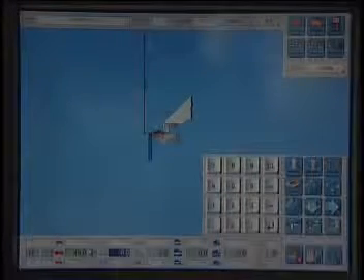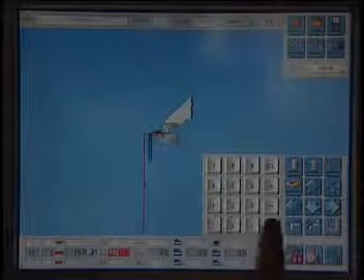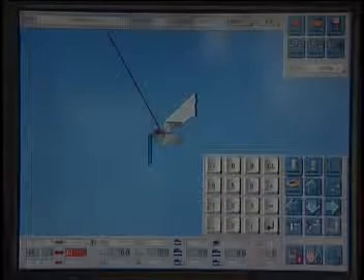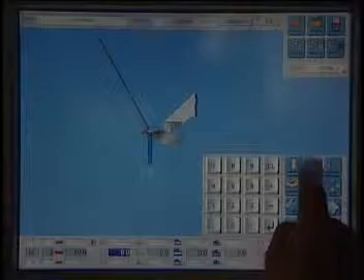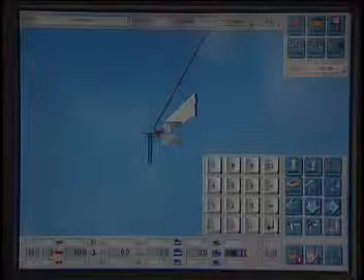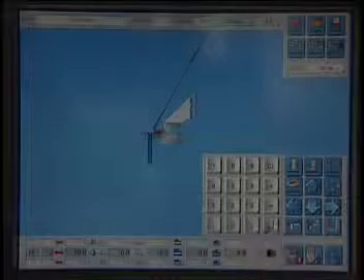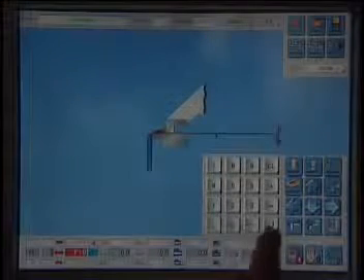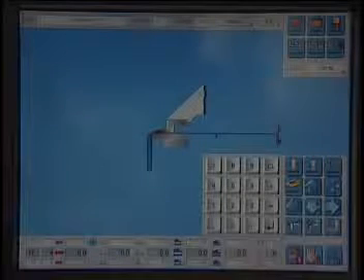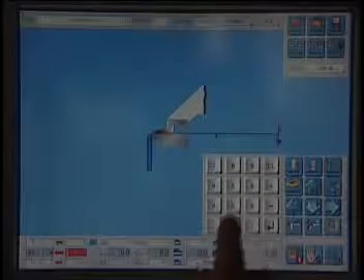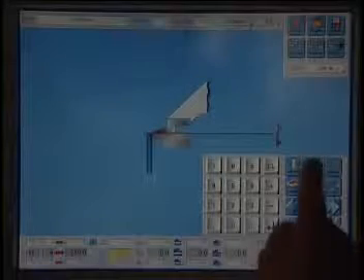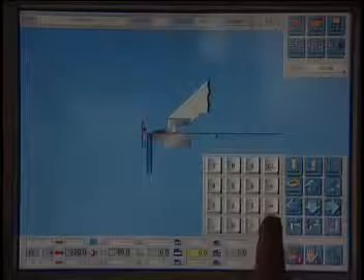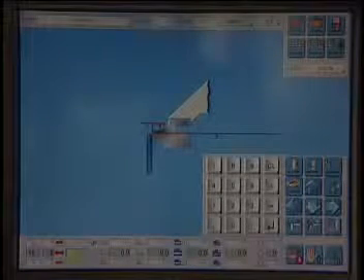Now we have to flip the profile. The third operation is to rotate our part and to hem it. To program a hem, enter a value into this column. To carry on, we have to reclamp our part onto flange number 0. Enter new backgauge value, rotate, and turn it around, 90 degrees bending angle, and groove side is ready.